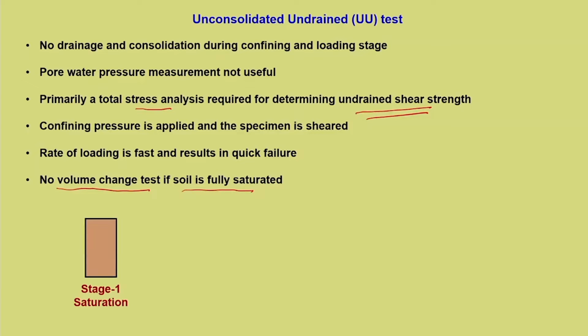The same thing is applicable here. If there is air present in the sample, then air will get displaced in the process. If it is fully saturated, whatever is the initial effective stress remains the same. But if you allow any sort of volume change, that will alter the initial effective stress, and once it is altered, the strength also gets affected. So, that is the reason. It is understood that no volume change takes place.